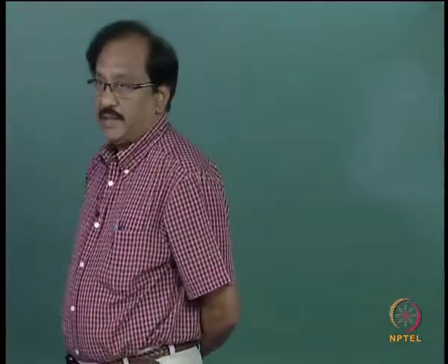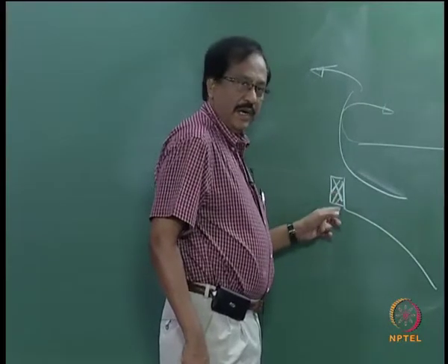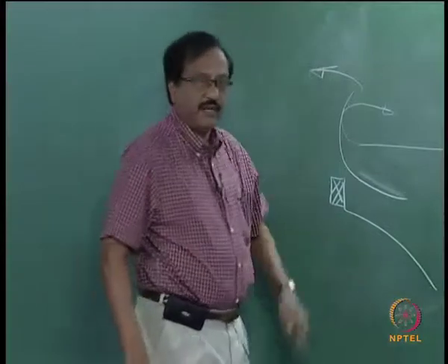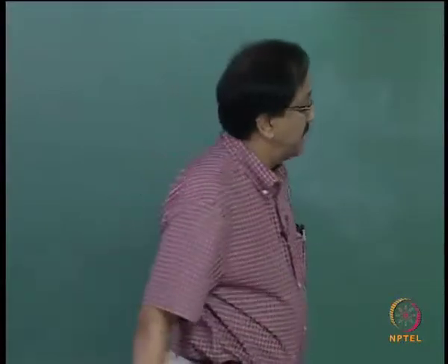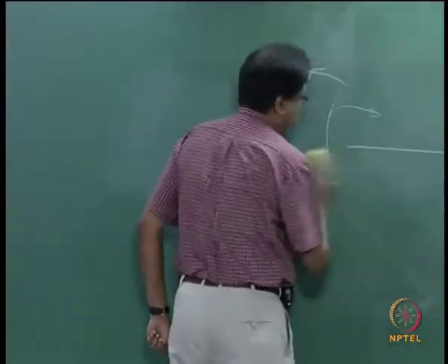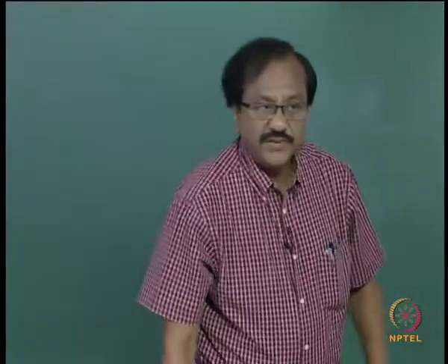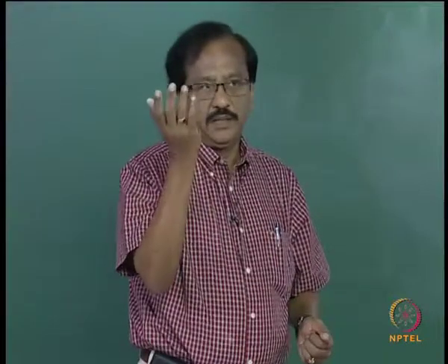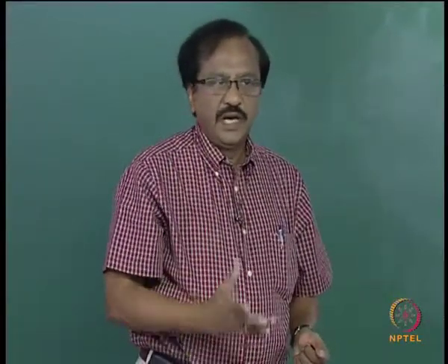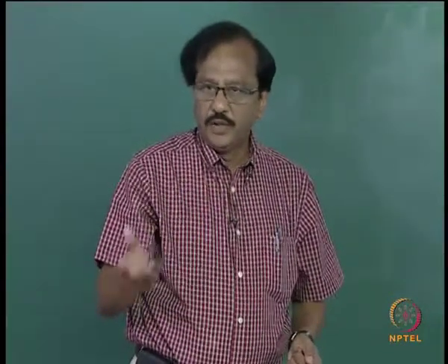This can be implemented later, but you have to make sure about the stability of this crown wall when it is implemented after the construction of the sea wall. Okay. So, this shows how these different types of sea walls are considered, and these are all non-energy absorbing, because the energy is not being absorbed and the energy is being spent either in the form of reflection or in the form of dissipation. Dissipation in the sense due to run up etc.